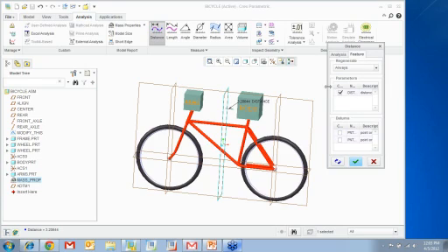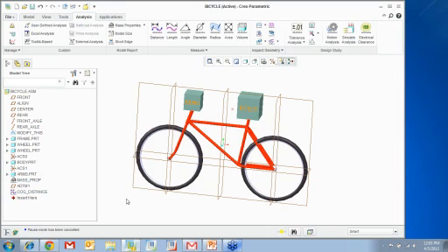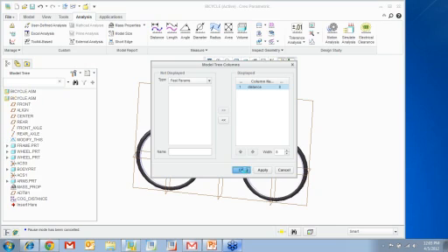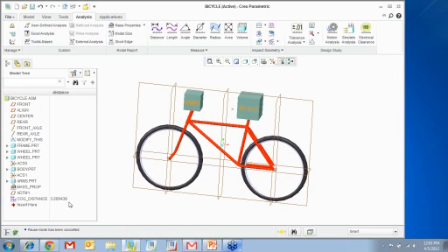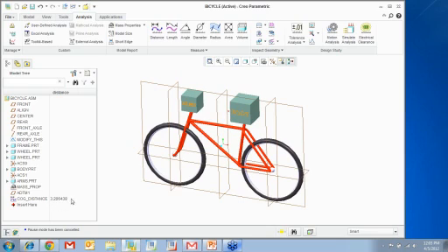Alright. You should also see that it will create a distance parameter for you. So if you want to know what the current distance is, you would go here to columns, feature parameters, and just type in distance. This is the name of the parameter that we want. So it will show you what the value is between the point and the plane. Anyhow, our idea is to minimize this particular distance to be 0.